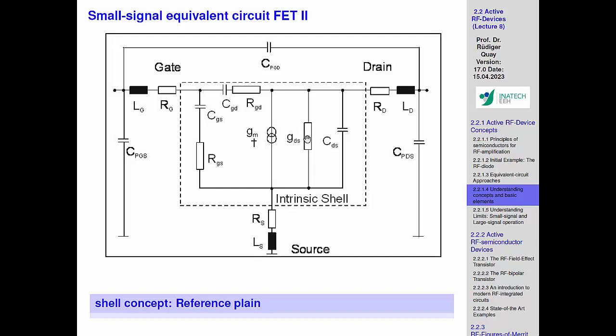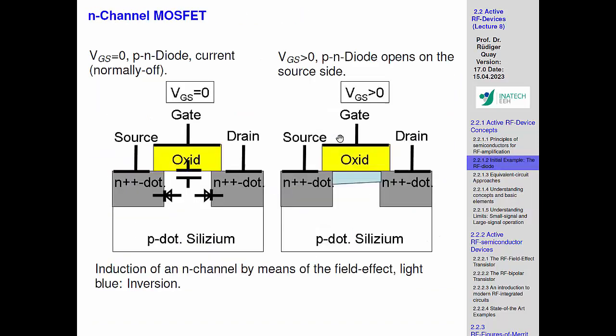This is this idea that we change current over high resistance. And the other thing is that apart from the input capacitance, there's also an output capacitance, which is understandable, I would say, because when you look at such a structure from source to drain, it's clear that something will couple between the two. And it's a dynamic equivalent of this resistance which we have at the output.